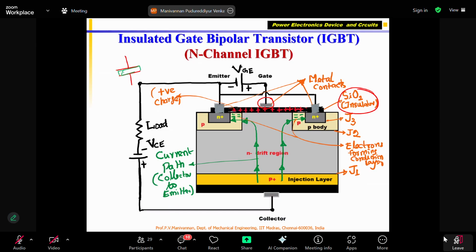This is my dielectric material, dielectric means non-conducting material, or insulator. Correct? One side we have one plate P1, the other one is P2, both are conducting plates. Please note that on one side N plus is a conducting region. It is not a metal like a pure capacitor, but still it is conducting.